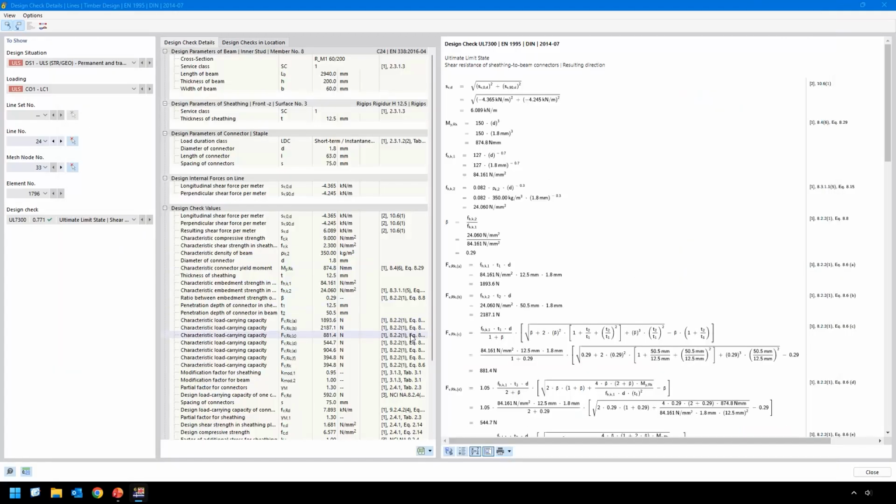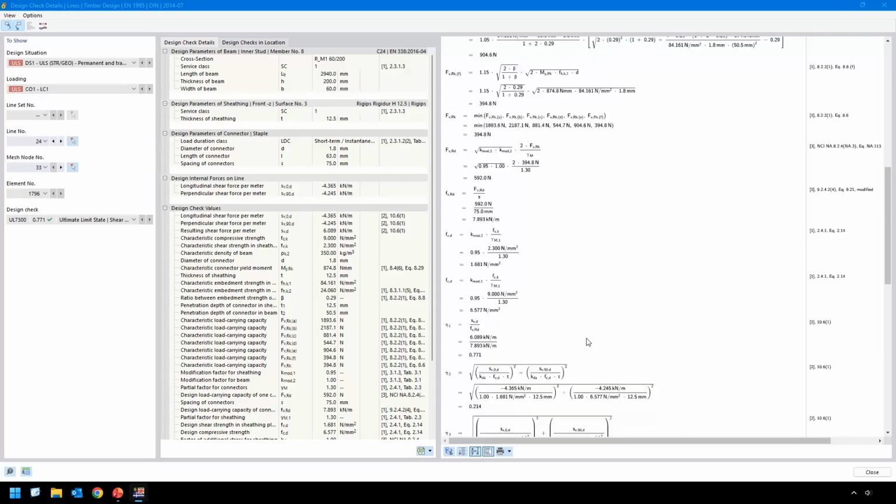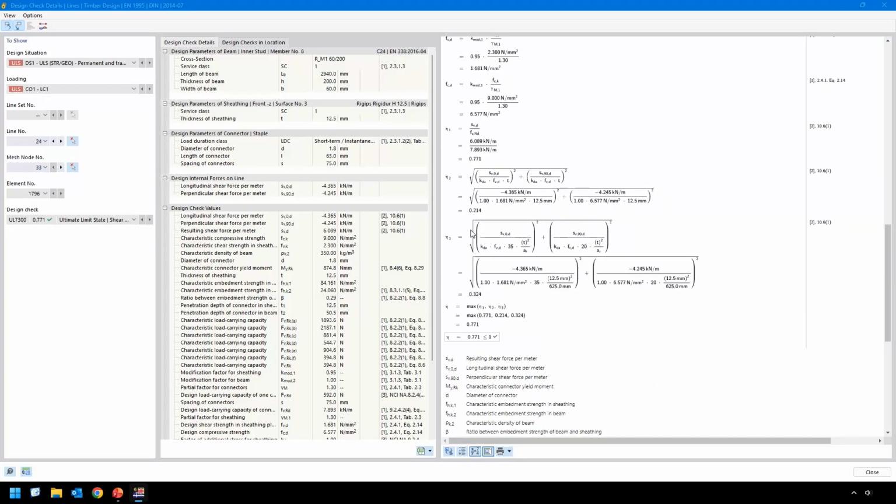On the very bottom, we see that this KV2 or KDA factor is considered with 1.0, because the standard says we need to use these reduction factors in terms of eccentricities. We don't consider it in our hand calculation, and in terms of stresses perpendicular to the grain, we fulfill this now in our FEA analysis.